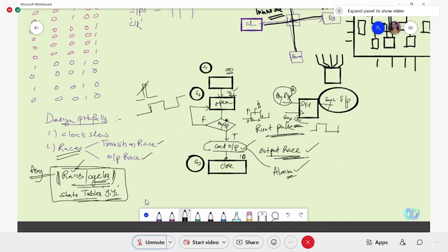And wherever you have any unexpected or asynchronous inputs happening, try to synchronize them using one extra circuitry of D flip-flop, or else the debugging of asynchronous designs becomes very difficult.